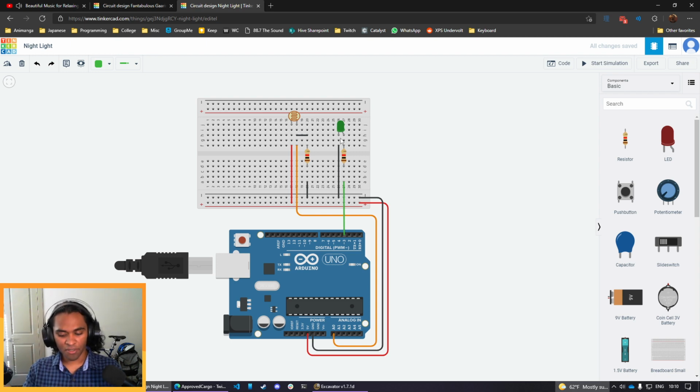With the keyboard, it's a bunch of rows and a bunch of columns of wires, so it creates a kind of grid system, if you will. How the keyboard can see which key I press is that it sees which row is selected and which column is selected, and it can bring it right down to that single key. So we can do a similar thing here, right? If we have a digital input, one that just goes high or low, like a light switch or a button or a keyboard switch or something like that.